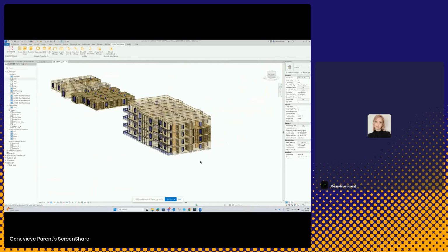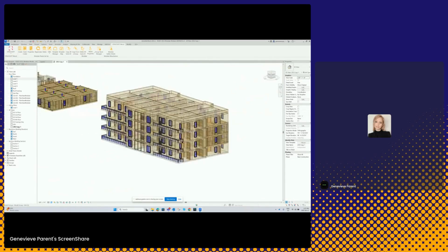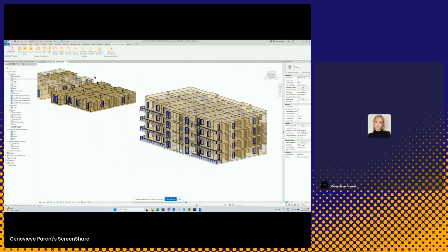And right now what we're going to do, we're going to do the reverse. We're going to copy from a group. So once I select, ooh, that's my bad. I'm going to select this group and I'm going to hit copy from a group. Our copy from a group will copy panel framing from a wall group that has framing to a wall group without framing. So I want to go steal that framing from that other group. Okay, I'll click on that. And it'll ask me that same prompt. What do you want to go and copy? I want to copy the walls and the floors.